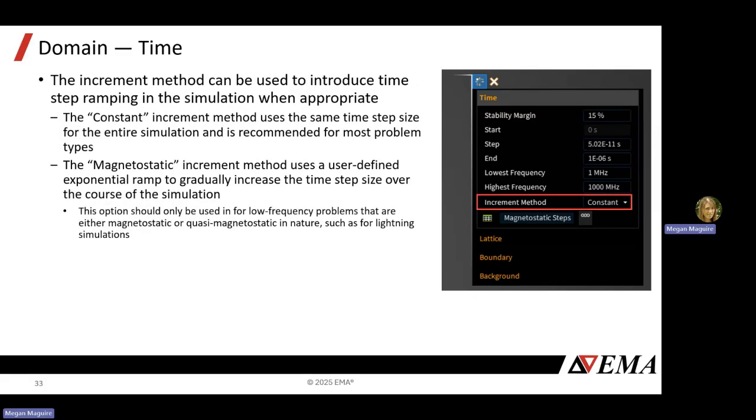The increment method is basically what it says: how does the time step increment. You can use constant, so the time step size will be the same throughout the entire simulation. This is recommended for most problem types.